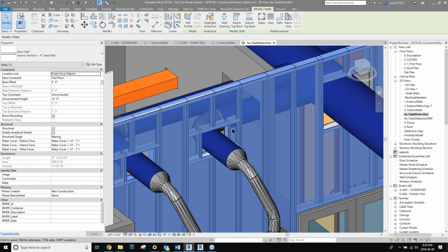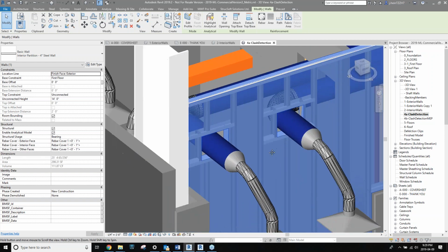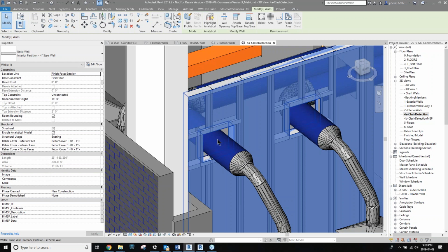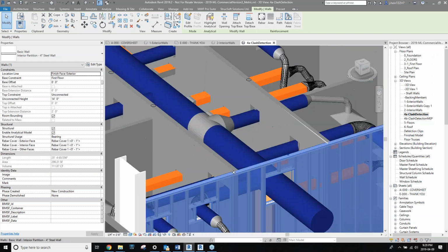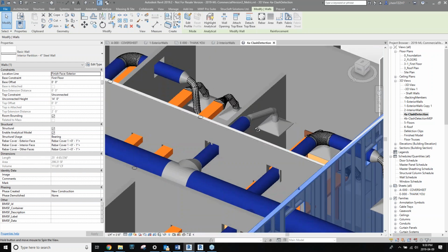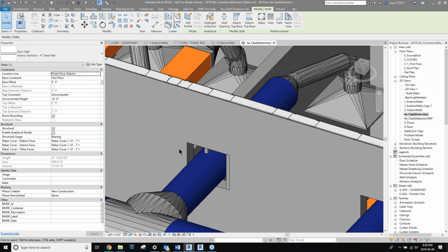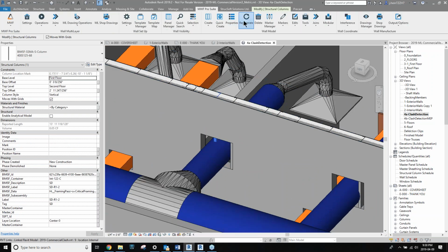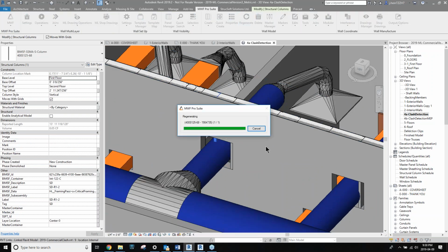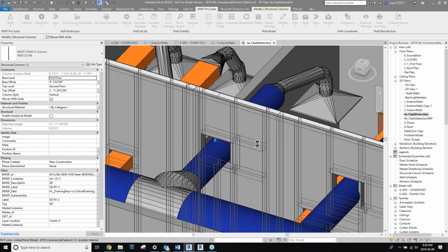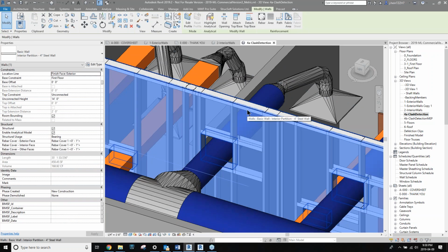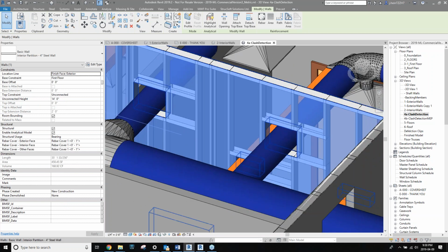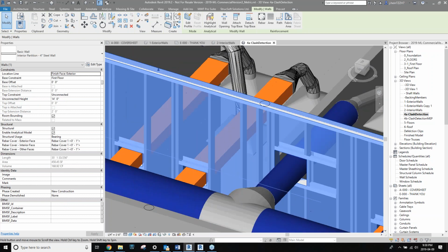Over here we get to 2 verticals and our horizontals go to nearest. Same thing here. It maintains the spacing and gives us our framing. Now, the wall that already was framed, you can see here that my framing still runs through the wall. All I do is grab any member of the panel and go up and regenerate like we did with the window, and this will now frame out this wall according to these new openings and new markers. So I will just grab the wall here so that it highlights out, and you can see we now have the framing that doesn't go through where the ducts are.